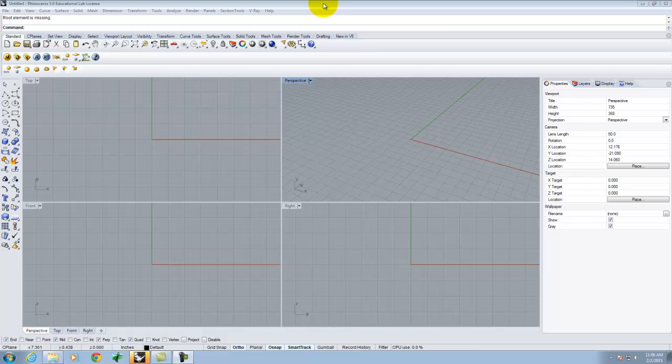So today's another day in basic shapes, but this one's a little more complicated than anything you've made so far, and it will reinforce a lot of the skills that we've already used, like lofting two curves together to create a surface. We'll do that. Patching a closed curve to create a surface. So it's a lot of those kinds of things.